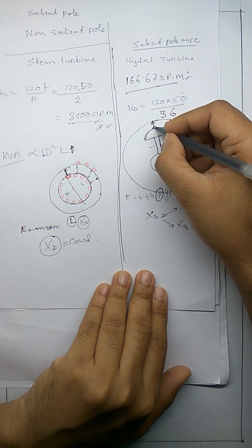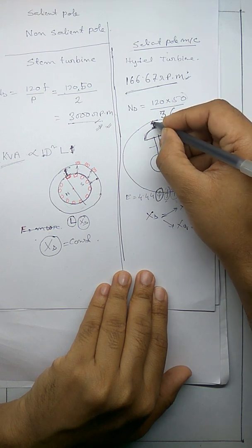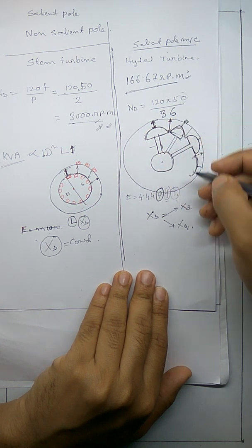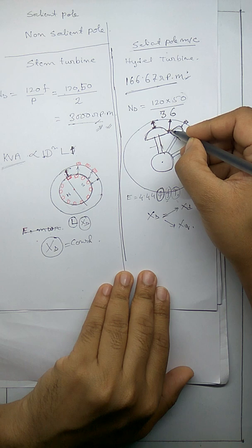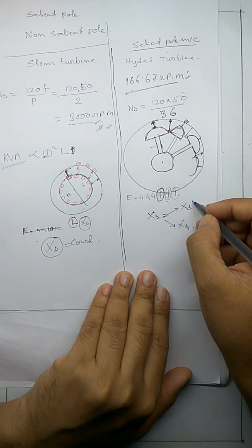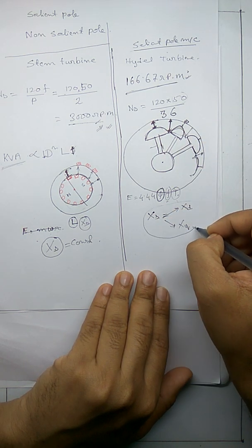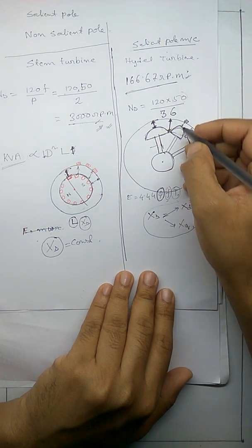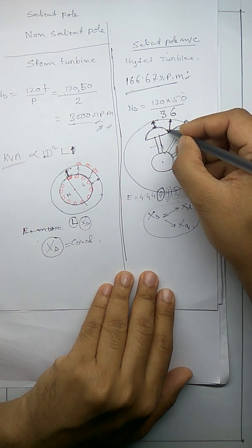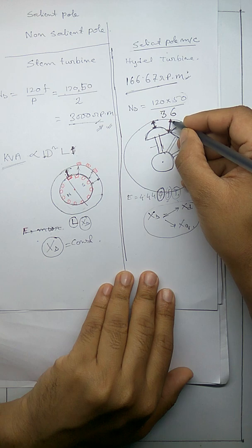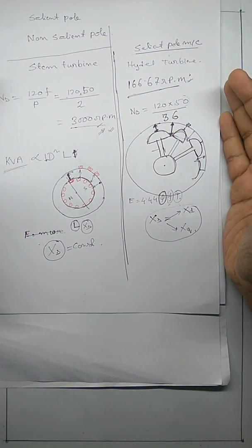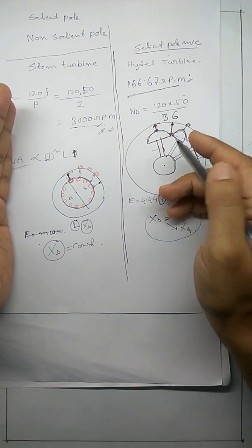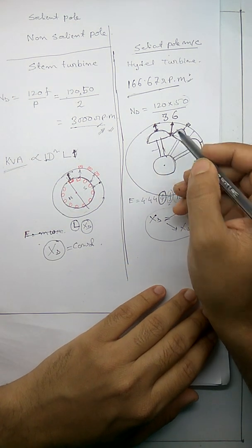This represents the reactance or inductance corresponding to the smaller air gap, and this represents the inductance corresponding to the larger air gap. So here I will do a calculation assuming that the reactance of the machine is variable and it varies with the location in the air gap. So in the next class we will see how to analyze a machine if the air gap is variable.